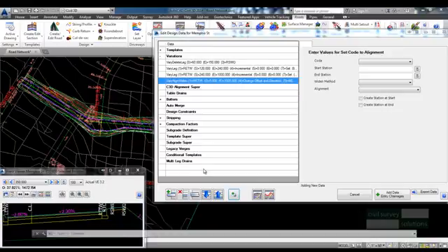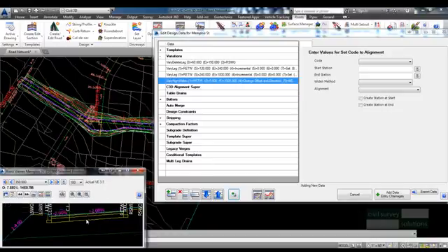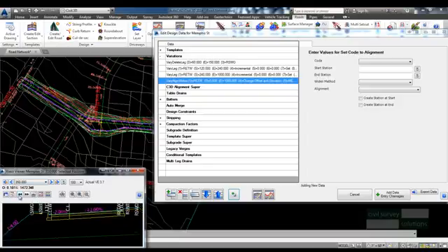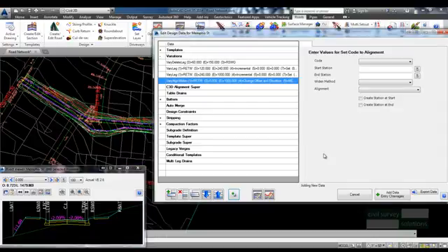It is not unusual to need to create extra sections in the cross-section to cater for such things as bus or parking bays, offsetting road crown, saw cut lines, or retaining walls. Anytime you want to add grade breaks in a cross-section, you either need to create and apply a new template or consider using the insert section variation.